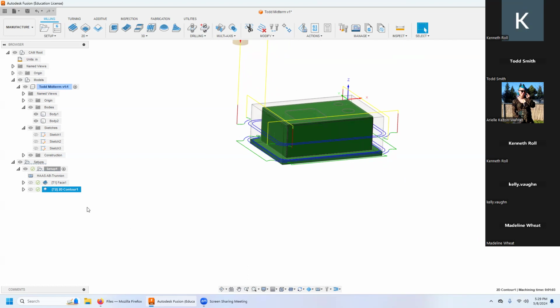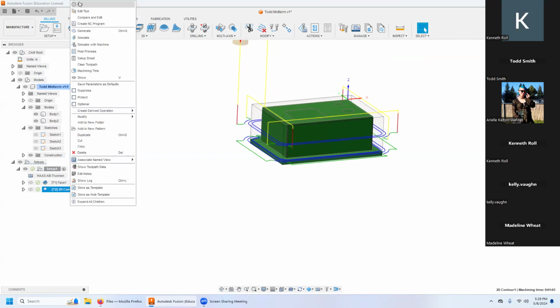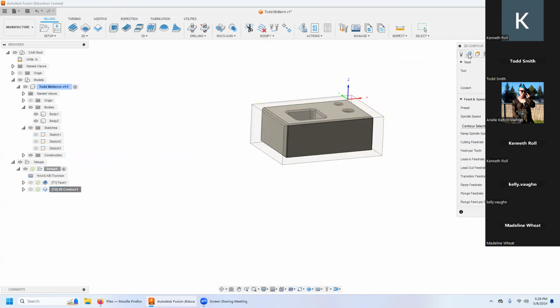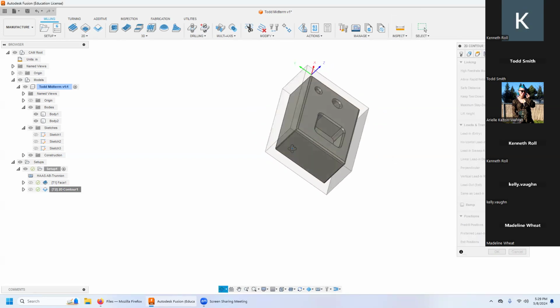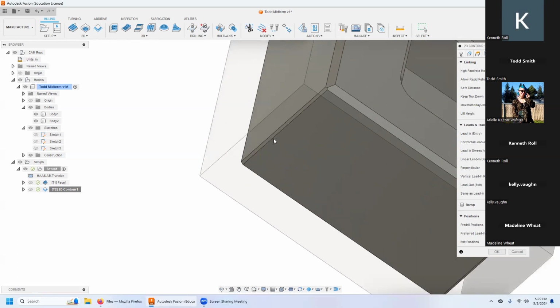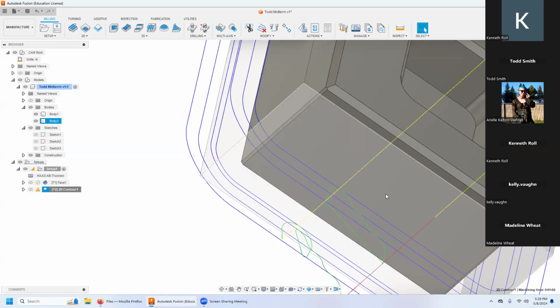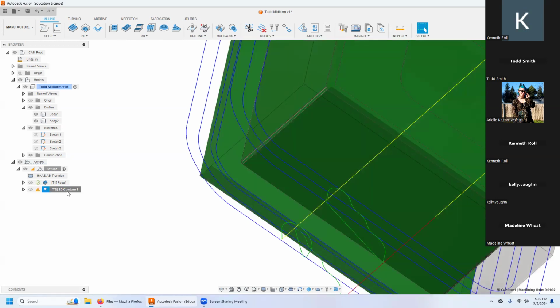If you want to be rid of that, then we can go into edit and go to geometry and turn off stock contour. Okay, linking. I'm going to kill that preferred lead in and go with a preferred exit and see if that will take. Nope, did not.